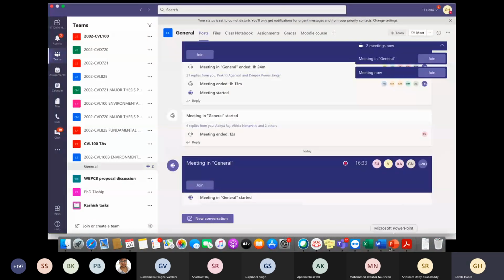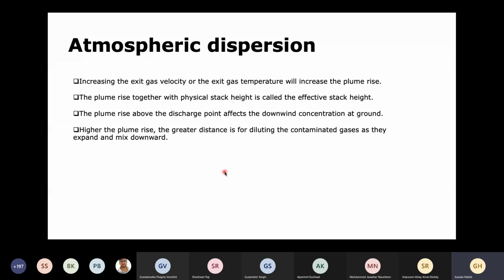Okay, so take two examples. One is for brick kiln, 100-meter height stack. Another is power plant, 200-meter height stack. The power plant is burning coal, which is high calorific value fuel, higher than the biomass. Biomass means agricultural residue, say any rye or sarso or pulse residue or maybe rice husk or whatever. So this particular biomass will have low calorific value, high moisture content.